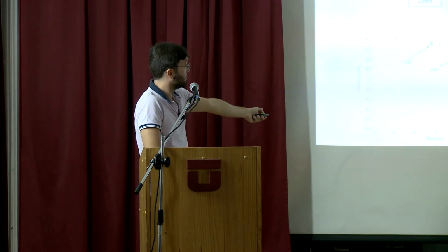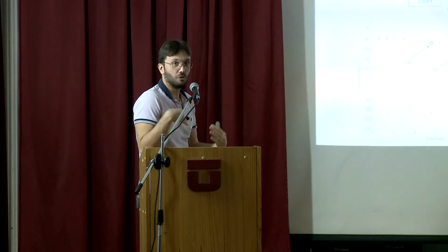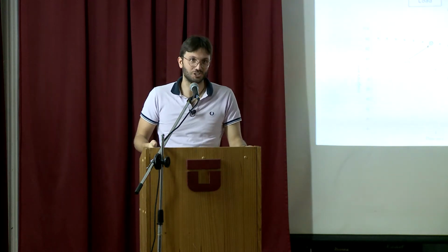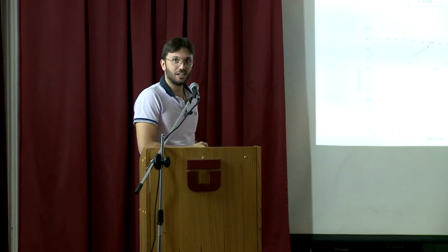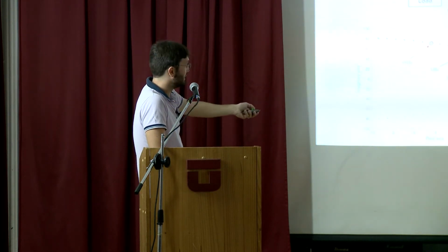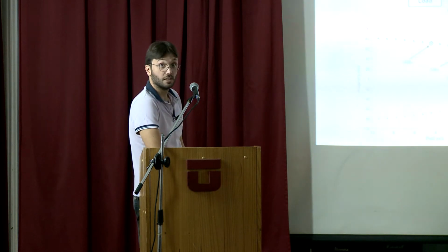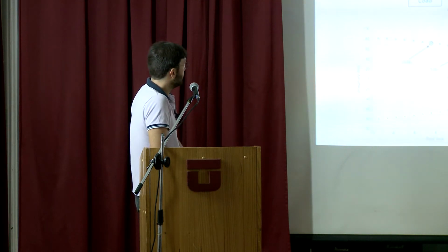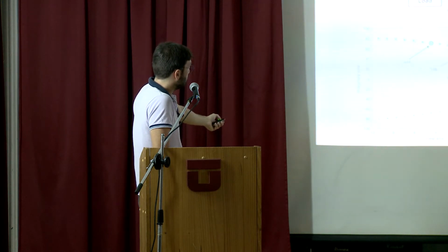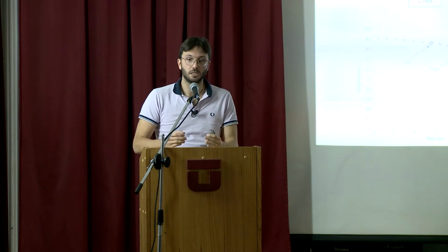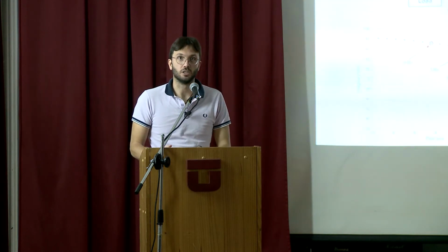Of course, at this point where we are in saturation, linear analysis is not valid anymore, but it is showing very well that it cannot work if the PLL is too slow. And again, we found really a perfect match between the analysis and the experimental result.